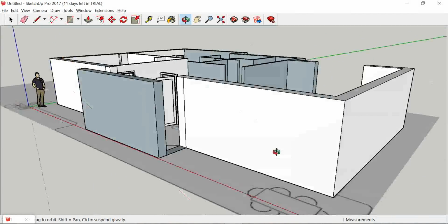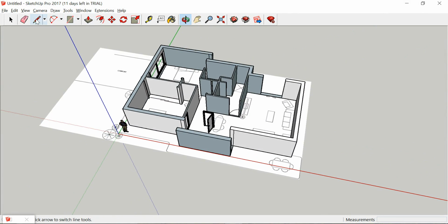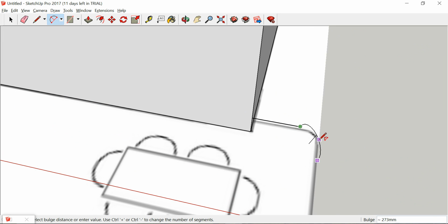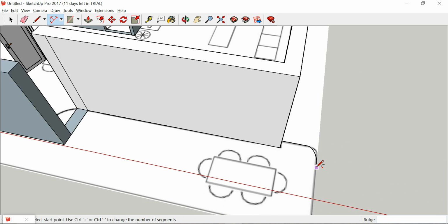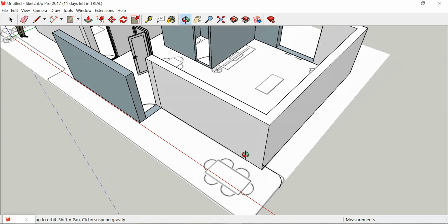I've also done on the other design the exterior. So I've included here where the grass goes, sorry, the paving. To do arcs, I tend to find a 2-point arc works the best. Click where you want it to go to, and then you click again for the actual arc of it, making sure it is on the correct orientation.